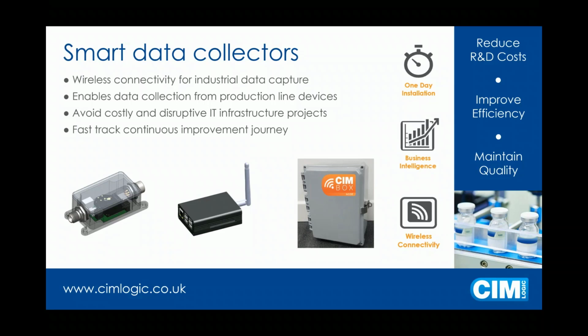Absolutely. And there is always the possibility, if you did want to use sensors that were already existing on the line, that there are ways you can piggyback off signals from sensors using optically isolated relays, for example. That means you can ensure the integrity of your existing validated systems and not get in the way of that. So there are lots of different ways you can think about getting that data.